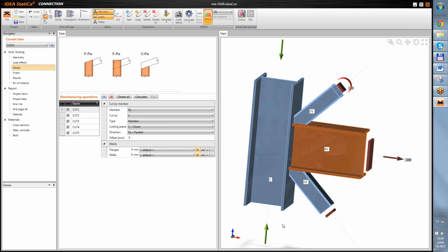Which forces from one component? Which component force goes to the weld, for instance? You have one weld and it connects two plates, a simple strip. You should be able to see that the total tension force goes into the weld and then goes out of the weld. Something like that. It's component based.